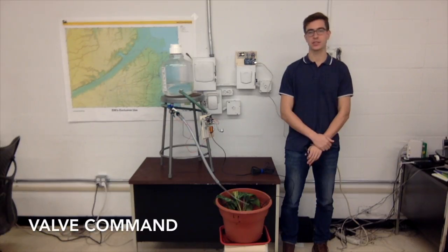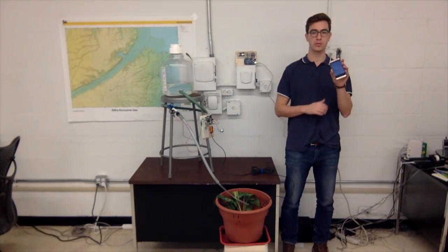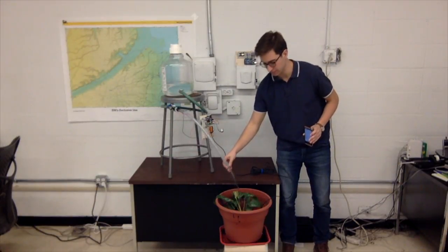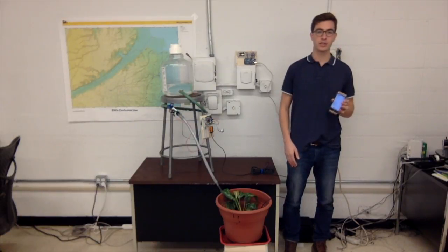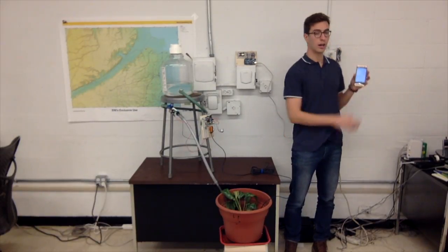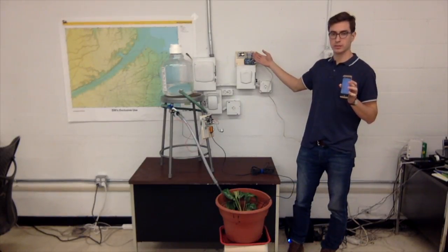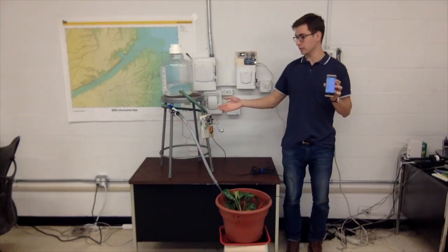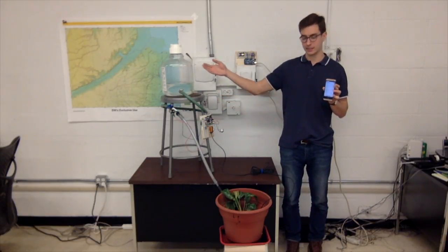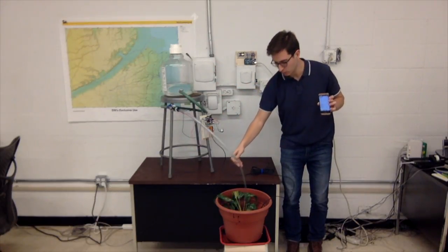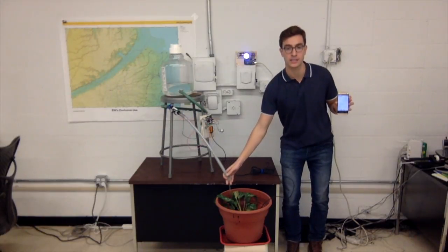This is the Intelligent Irrigation System prototype. Here we will show you how you can send a command from a phone to irrigate a plant. The information flow is as follows. First, a command is sent from the phone up to the cloud. The cloud then sends the command to the coordinator Zigbee, which sends it to the receiver Zigbee. The receiver Zigbee then sends a valve command to open a valve that is connected to a tank. At which point, water begins flowing into the plant, where the moisture is recorded by a sensor in the field.